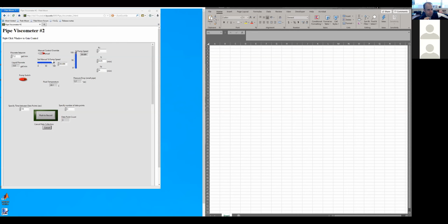This lab, you really don't care if it's laminar or turbulent in the sense that all you're really looking at is pressure drops. What's the second dimensionless number? You're probably not going to think of this one. It's not Nusselt number. It's not Prandtl number. You have to worry about those if you're dealing with heat transfer, but it has to do with compressed gases. If you have to worry about compressible effects, does anyone know what number that is? You probably didn't talk too much about it in fluids, but it's the Mach number.